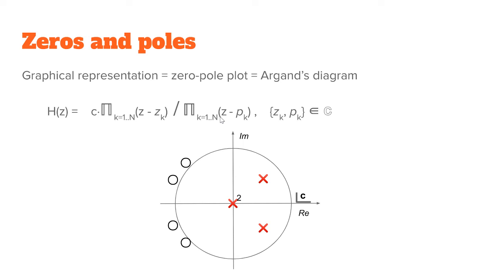Right. Have you done this kind of diagrams? Yes. In an RC filter, you have a single pole here. Or if you have more stages on an RC filter, then they will be on the real axis. But with Sallen-Key systems, you can put these poles so that you would get different kinds of properties for the passband. Alrighty.